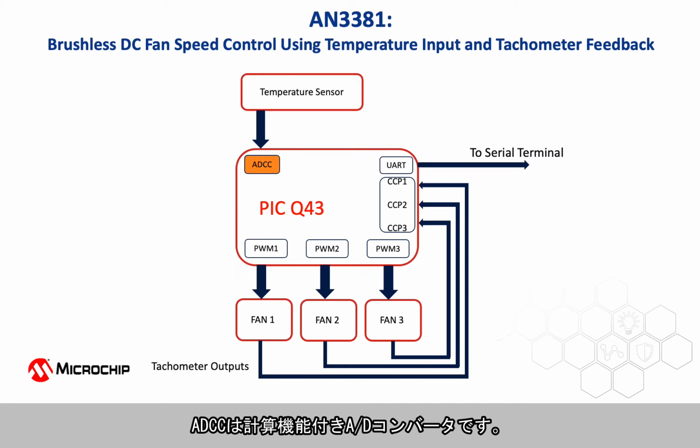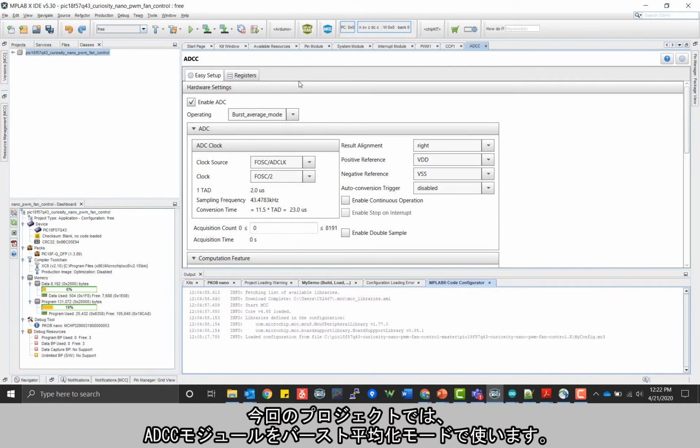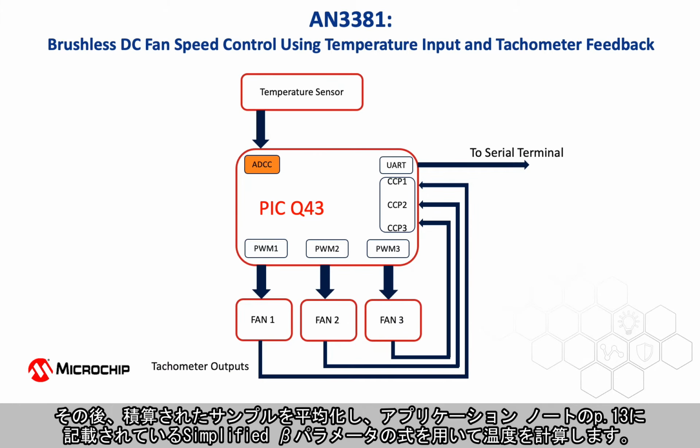The ADCC is an analog to digital converter with computation. It has built-in computational features that provide post-processing functions, such as oversampling, averaging, and low-pass filtering. In this particular project, the ADCC peripheral is being used in burst average mode. In this mode, a single ADC trigger event causes the ADC to accumulate samples until the number of samples matches the value in the ADC repeat setting register. Then the accumulated samples are averaged and the temperature is calculated using the simplified beta parameter equation shown on page 13 of the app note.